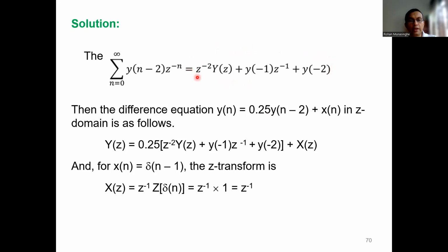So on the right-hand side of this equation is the Z transform of the shifted sequence, y[n-2]. When you transform this into the Z domain, it will look like this. Not only the first term here, z to the minus 2. Why is it? This is what you see in the table, because the table has been created for double-sided sequences.